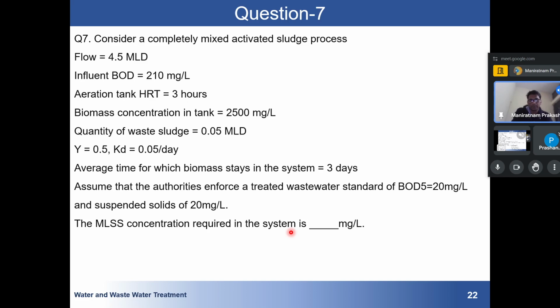It has defined that when you are discharging wastewater, first you have to treat it in such a way that certain parameters such as BOD, DO, suspended solids, nitrogen content, phosphorus content, and pH of the system should be within a limit, and that is known as the CPCB limit.